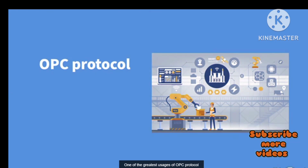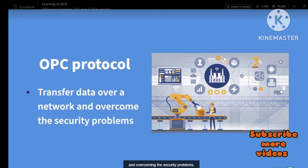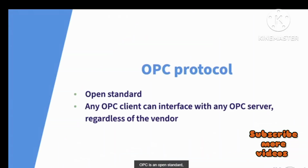One of the greatest usages of the OPC protocol is to transfer data over a network and overcome the security problems. And this actually helps in SCADA systems. OPC is an open standard, which means any OPC client can interface with and request data from any OPC server regardless of the vendor.